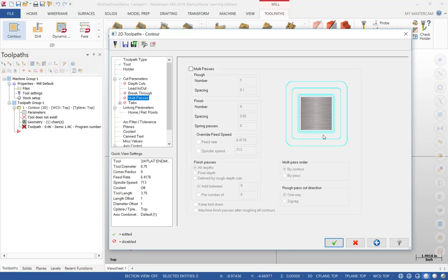You don't have to create different offset drawings to cut roughing cuts, a second one, another one, and another one. You can just do that all in this setting. But in this example, I'm going to leave it unchecked just because I do not have to do the multi-pass. It's one final cut. Tab, I'm going to skip that for now.